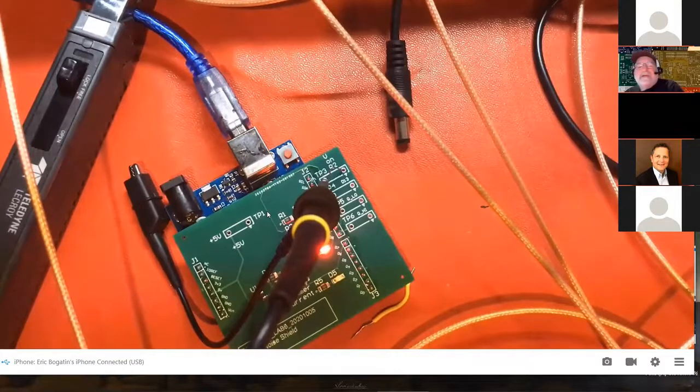The second, though, is because we're measuring a small voltage on top of a larger voltage, you want to make sure you have a good common mode rejection ratio. For this particular probe that we were using here, when we're on the most sensitive scale, we had a little more than 5-volt common mode voltage that we could tolerate, and we were below that for this example. For the less sensitive scale, we can go up to a 50-volt common mode voltage range for this probe, and 60 for our new high bandwidth probe.